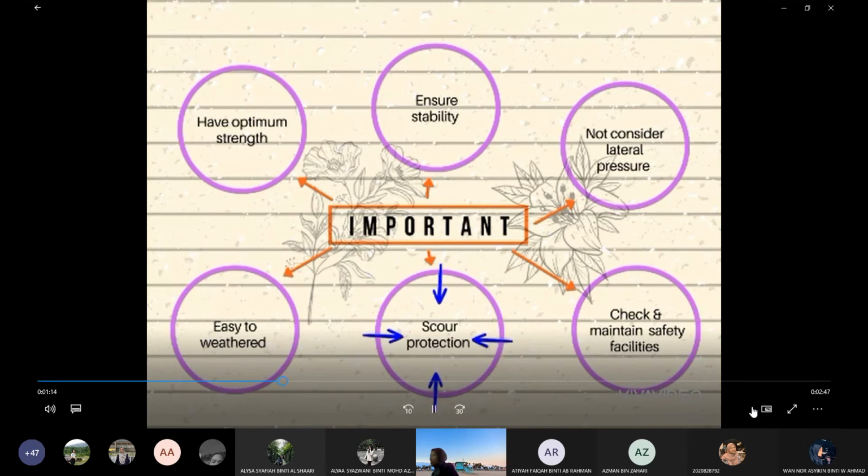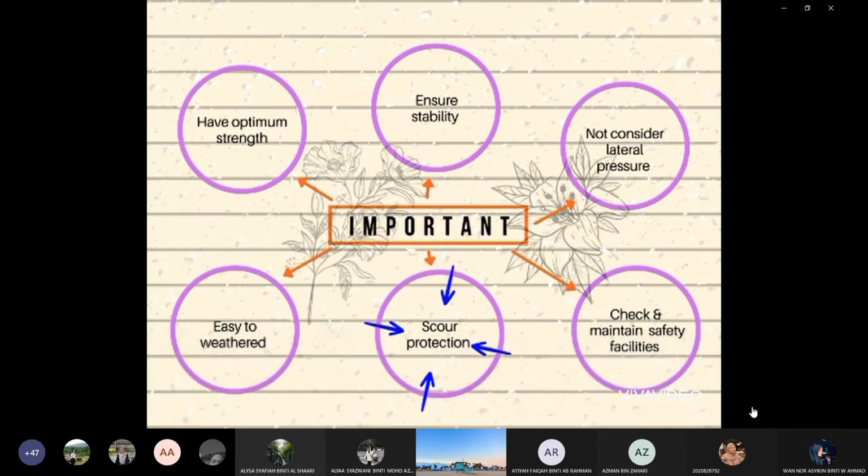Other than that is core protection. It happens at section of small water flow rate or weak flow destructive effect, using paving stone, pannier and precast slab. So, it protects subgrade side slope along the river. Lastly, for high and steep protective structure, safety facilities should be set to check and maintain when design and construction.